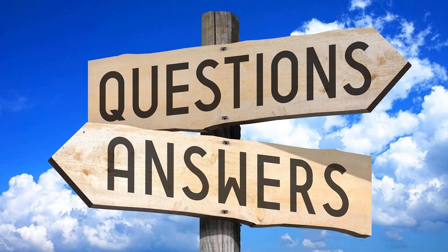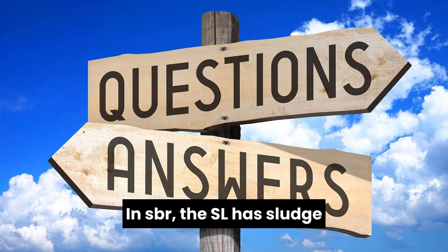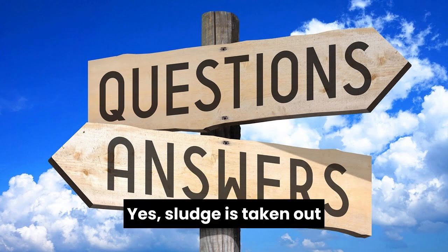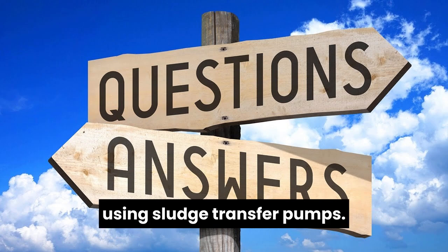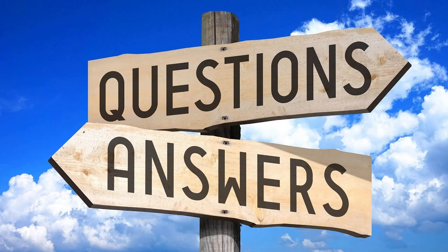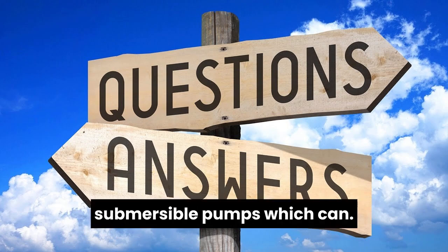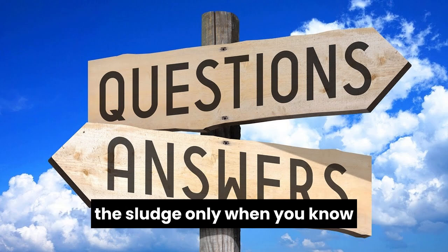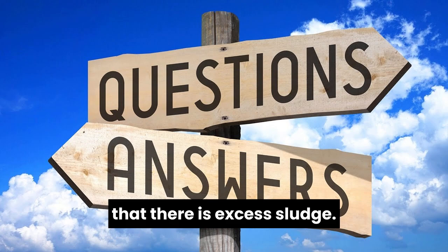Hello. Yeah, please go ahead. I have a question here. In SBR, the sludge has to be taken out. How can we process and take out this sludge? Sludge is taken out using sludge transfer pumps. There are pumps installed in your SBR. Most of the time, they are submersible pumps which are designed for handling sludge. And you have to take out the sludge only when you know that there is excess sludge.